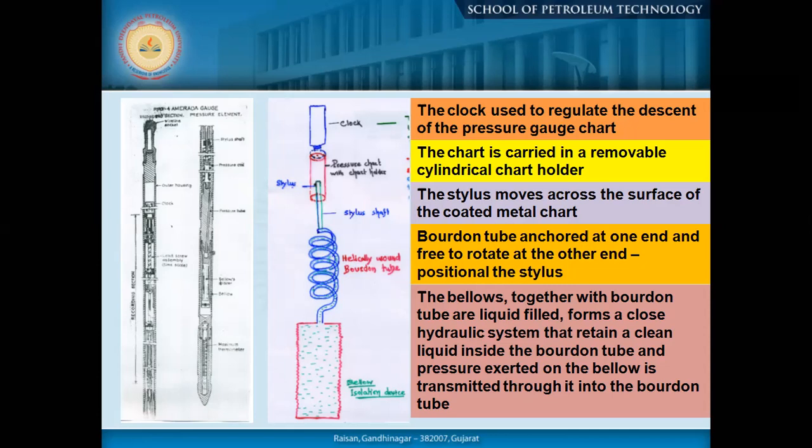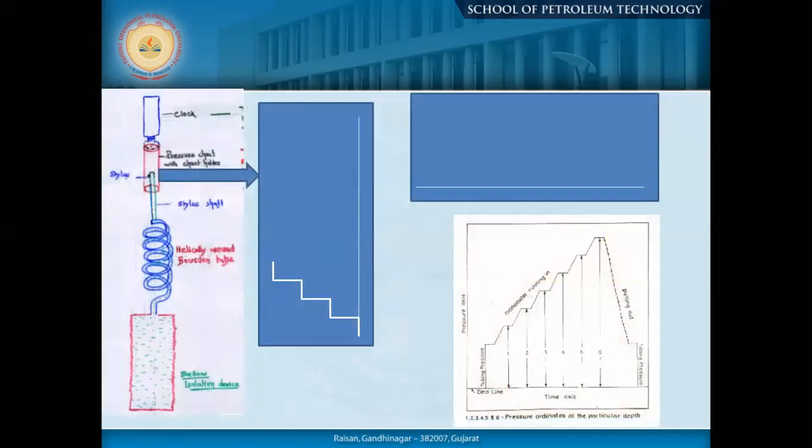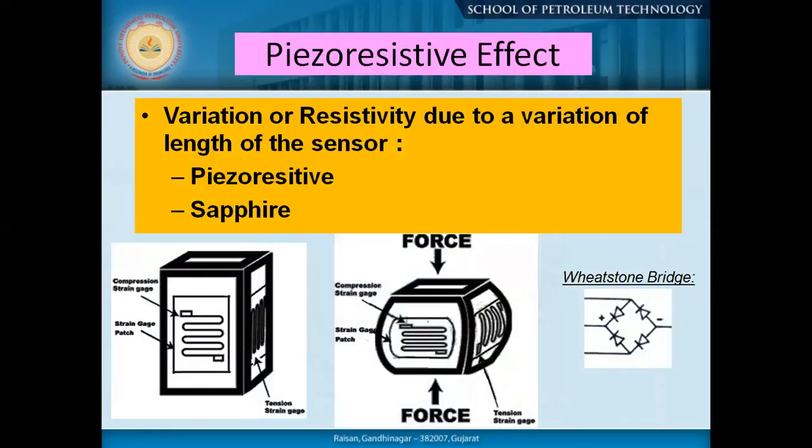Yes, these are Bourdon tubes actually. Okay, a mechanical gauge, and now it is no more in the industry. This is how it marked, and that gives us the pressure value. I'm not going into it because it is not in the industry now. Industry now has this sort of thing: piezoresistive mineral, piezoelectric mineral quartz, and piezoresistive sapphire. These are now used. Just giving you a broad idea.